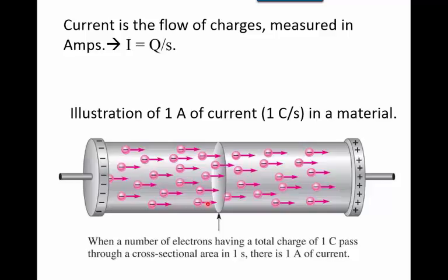If you have a big conductor, technically you could carry more current, but without the wire burning up. In a small conductor, because there's some heating that goes on, the electrons are bouncing around atom to atom. They're literally going from one copper atom to the next copper atom, jumping the shells because they move off easily. But that's an atomic vibration, and it will make the wire heat up. So if you try to put too many coulombs, too much current, through a wire per second, the wire will get hot. If you need to carry a larger capacity of current, you need a larger wire.